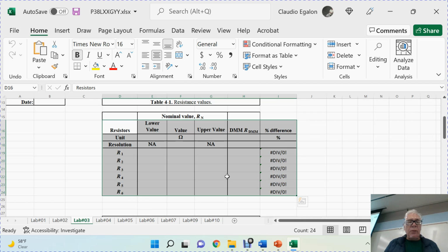But let's concentrate on this one, okay? I'm going to get one of those resistors. I'm going to show you how you're going to measure their resistance. Here's my resistor. Here's my multimeter. Black with black, red with red. For a single resistor, you're not going to need the proto board, okay? For a single resistor, here you go.